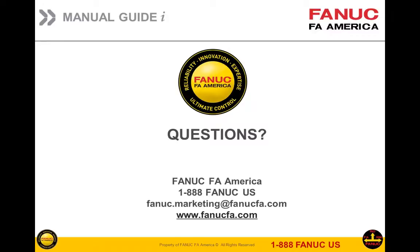All right, okay. Another question here. A lot of good questions mean it was a good presentation here. I'm always glad to see this. When milling a freeform, can you mill only from point A to point B, or does it have to be a complete box? It is because there are cycles within the contouring part where it's only a partial contour. So yes, you can just do a straight line. Yes, is the answer.